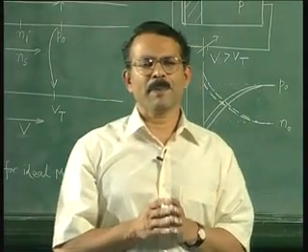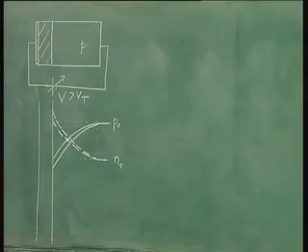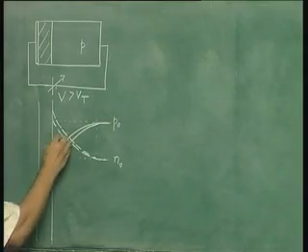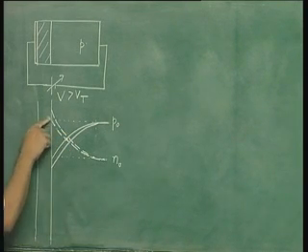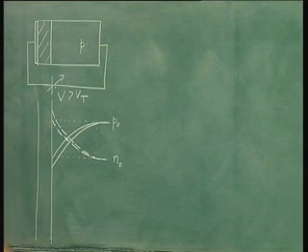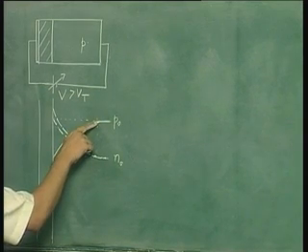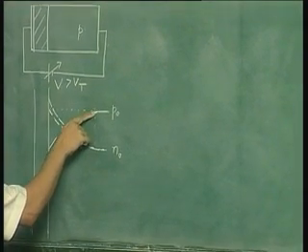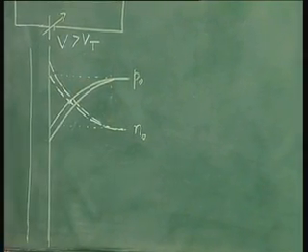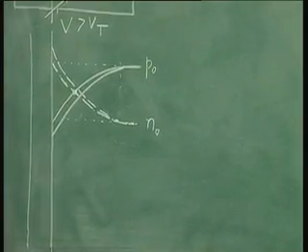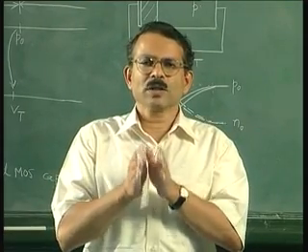You will recall from the p-n junction depletion region analysis that even there you had an intrinsic point. Now coming back to the concentrations, this is electrons and these are holes, you find that Ns is now more than P naught. What is interesting to note is that this depletion edge, the edge of the depletion layer, will not change very significantly beyond threshold. This is the important point that we must understand, that the depletion region almost ceases to expand beyond the threshold voltage point.